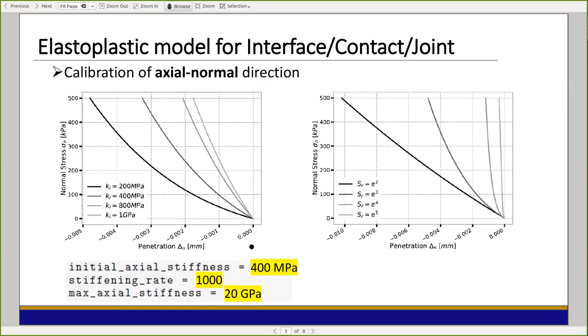Yes, Professor. So just to note, this is really one stiff material, concrete or steel, on a relatively soft material, either softer rock or soil. In this case, what you have is a number of particles, and you have something very stiff on top. This is the reason why the stiffness is not immediately going up, why the forces are essentially exponential.